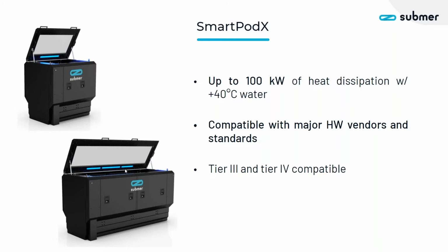This one-phase liquid cools down the servers and maintains a proper temperature during operating conditions. And this Smart Coolant is cooled down with a heat exchanger with a secondary cooling circuit, which flows with water.